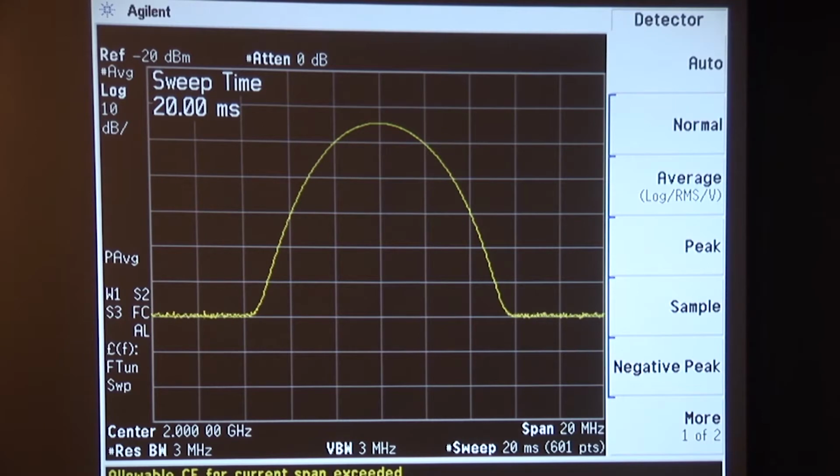So here's a carrier wave signal. Now, in the time domain, this signal looks like a sine wave. In the frequency domain, what we see here is a bump, and this bump, if we measure its width at the 3 dB point, where the amplitude on this curve is 3 dB below the maximum level here, we'll see that in fact that bandwidth is 3 megahertz right there.